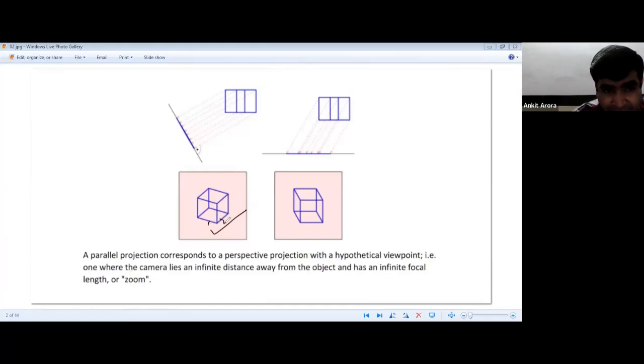So it is different to an isometric view also, how it is shown here. So if you see these faces, these lines are same, right? Had this been perspective, this would have moved towards a vanishing point. But here, they are all parallel, and the distance is always same. In this side also, so if it is a cube, it is a cube. It is a very basic thing, I think. But then again, these terminologies may confuse you in the examination. So just do remember that. So how the projections are happening, it is shown in the above images also.